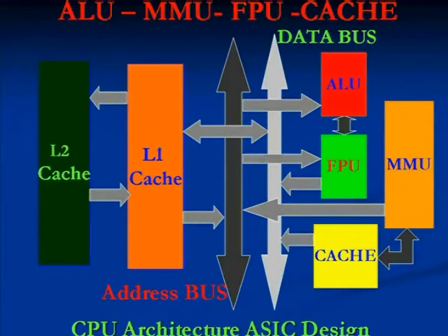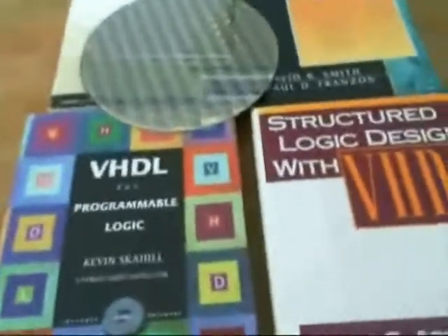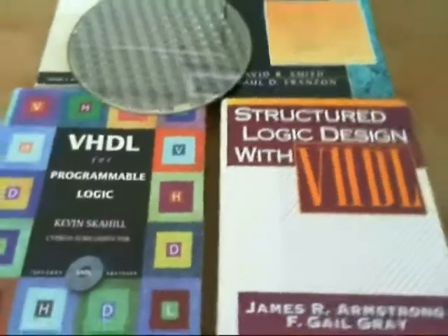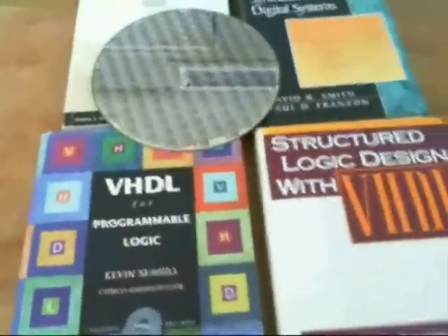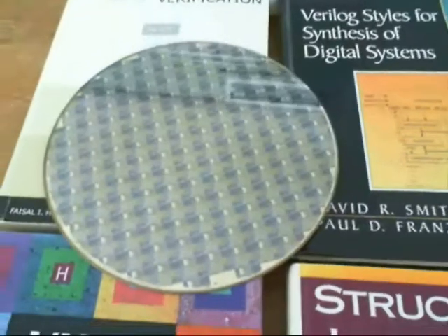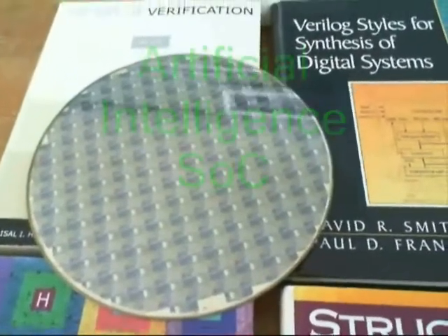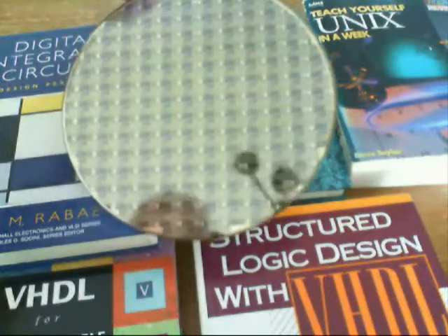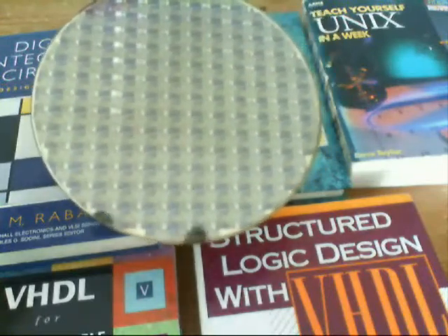The first step was to do floor planning, which is the process of placing the various blocks and the I/O pads across the chip area based on the design constraints. Then placement of physical elements within each block and integration of all analog blocks or external intellectual property cores is performed.